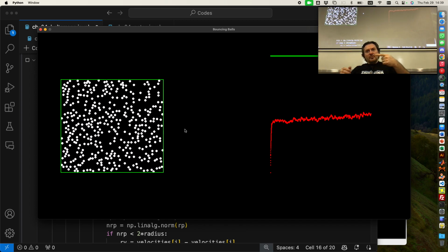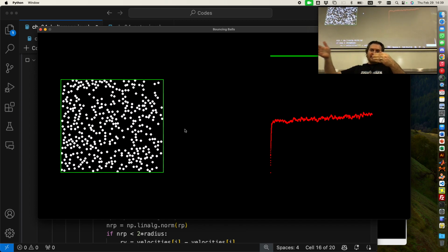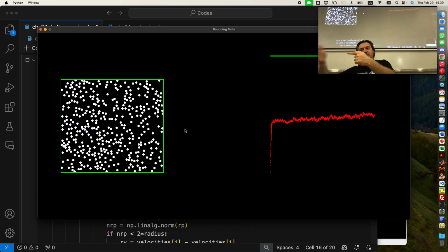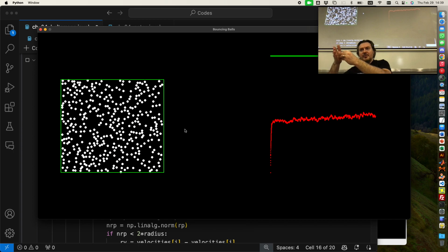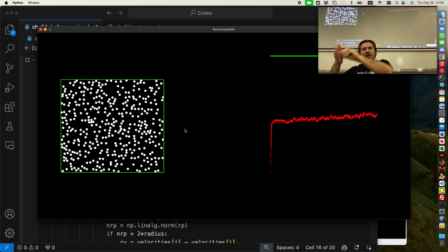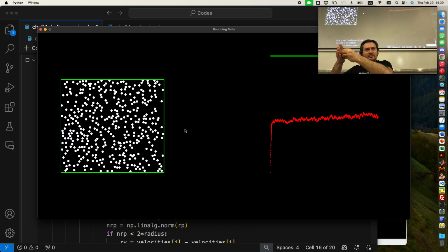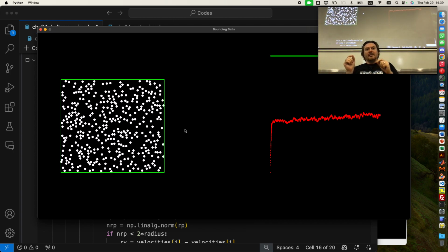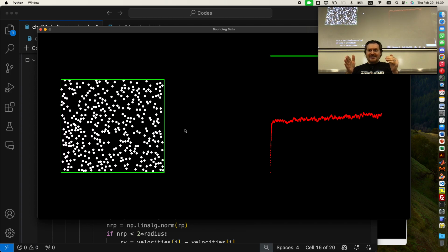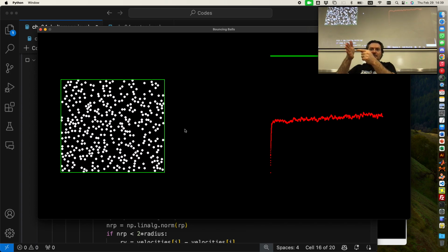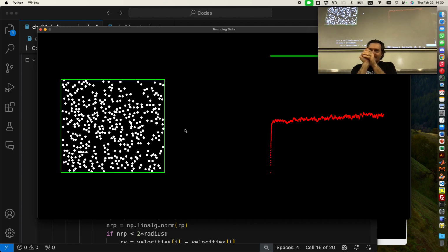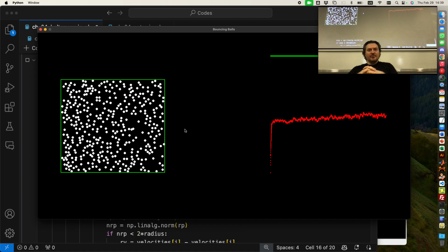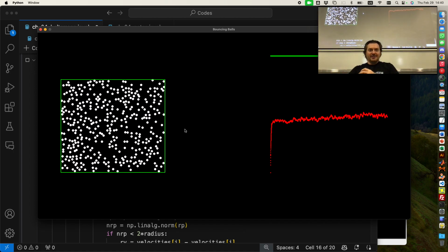Nevertheless, the ones that are hitting with 500 meters per second, since I'm moving the wall ever so slightly, when it hits it, now let me increase this. You hit a ball with a tennis racket that was moving like this. What happens to the ball? It doesn't just bounce back with the same velocity. Its bouncing back is decreased. So the gas molecules that are hitting the piston are losing their velocity ever so slightly, but that is enough for the whole effect to happen, the cooling.